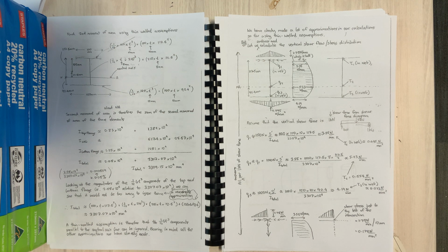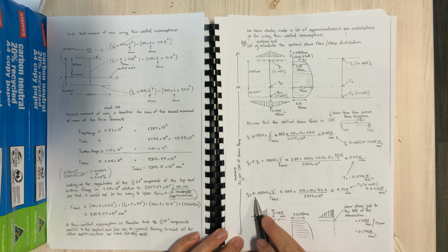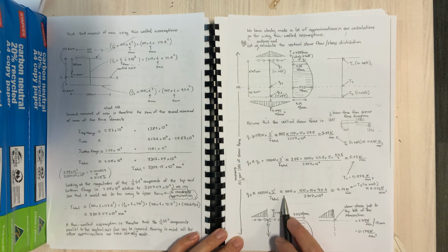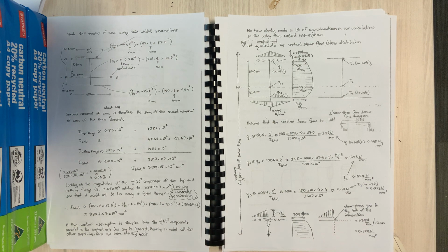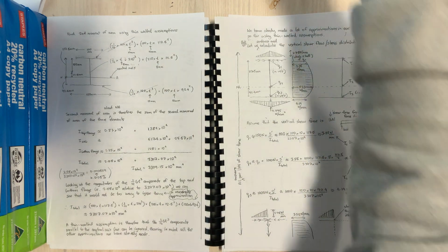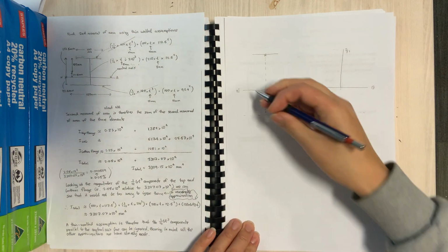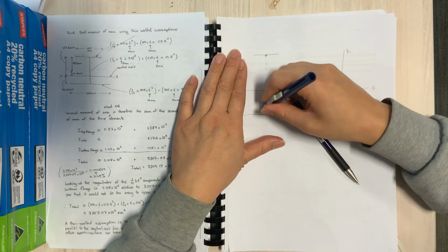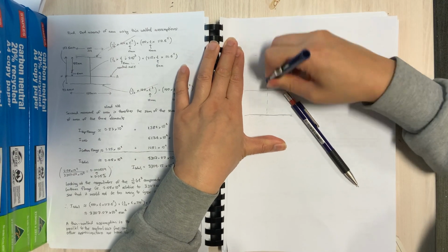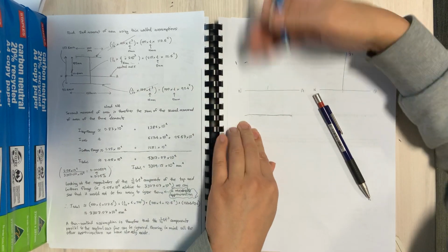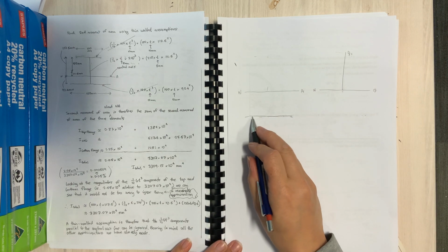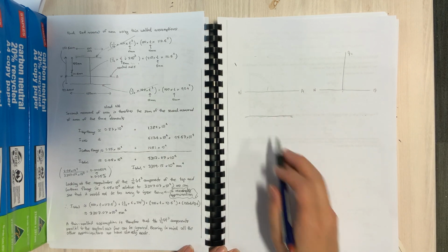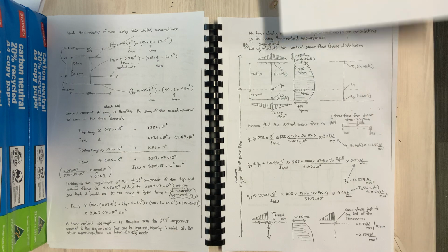And then the last one here is Q3, and again, same thing. Let's check this one here. So again, what we've done to work out the Q3 is we'll concentrate on that bit there, and then we'll pretend that the rest of the section disappears, and then that area times that distance would give you the S dash.